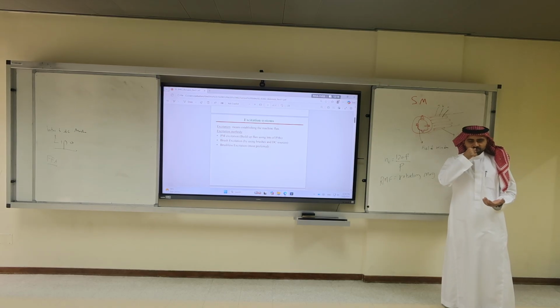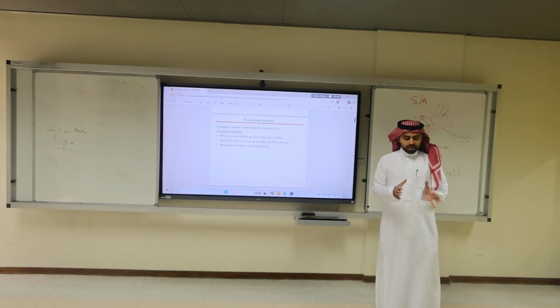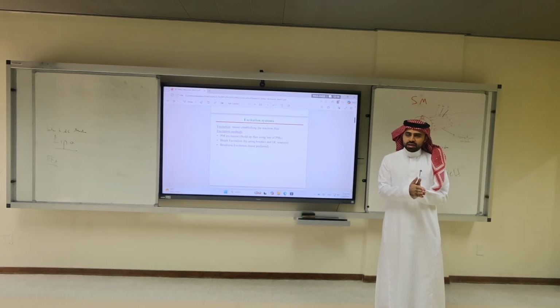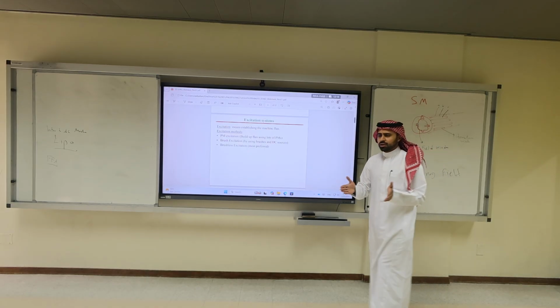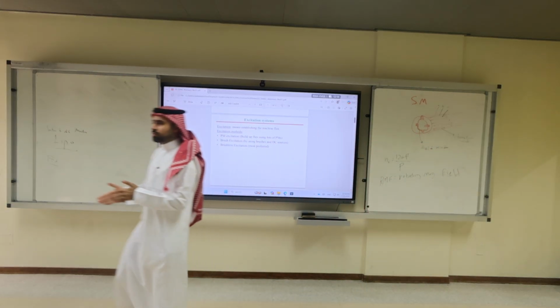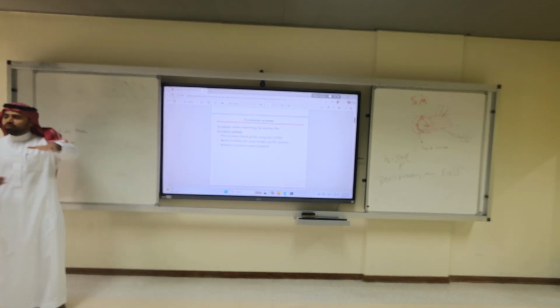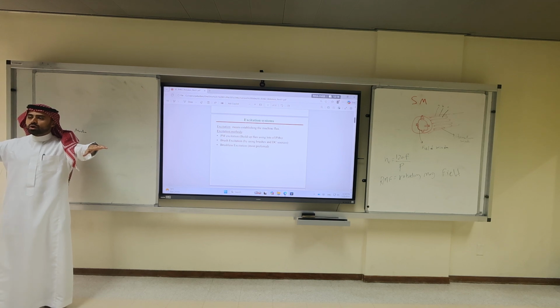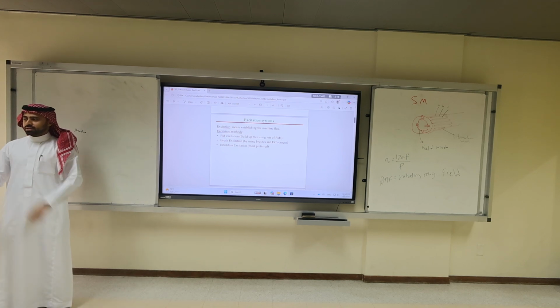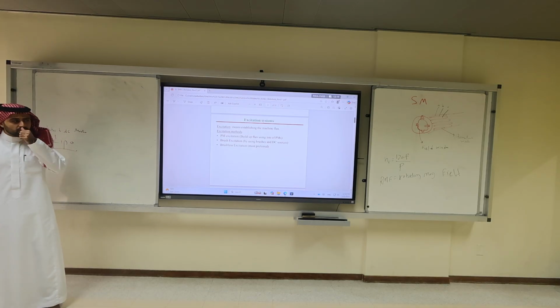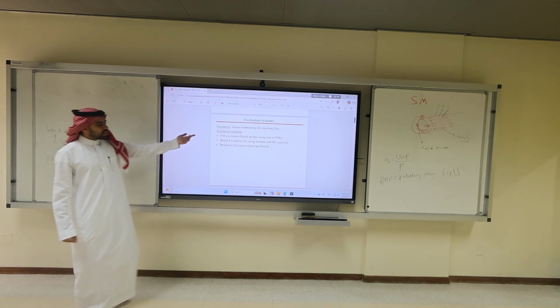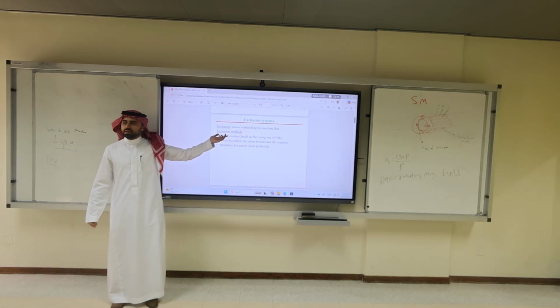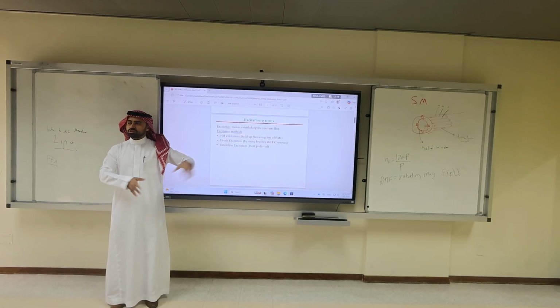That's why if you look at EVs, if I'm not mistaken, usually they say 10 years or maybe 200,000 kilometers. Usually you achieve it, and after that, 10 years, you have to change the traction system. They have to put in a new permanent magnet, they have to look at the inverter. So this is not practical. You can't go to a small generator and change it every 10 years.